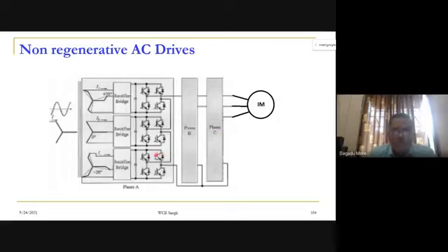One H bridge we have shown here. These supplies are separate. So how many secondary windings do we require? One leg requires 3 windings, another leg requires 3 windings, and the third leg requires 3 windings. So what kind of transformer do we have? One primary winding which is star connected, and how many secondary windings do we require?